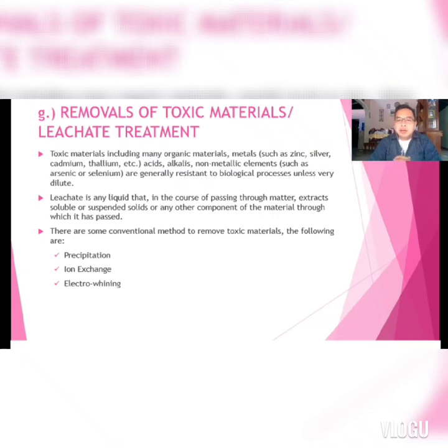Electrocoagulation is an electrochemical approach which uses an electrical current to remove metals from solution. An electrocoagulation system is also effective in removing suspended solids, dissolved metals, tannins, and dyes. The contaminants present in the wastewaters are maintained in solution by electrical charges. When these ions and other charged particles are neutralized with ions of opposite electrical charges provided by the electrocoagulation system, they become destabilized and precipitate in a stable form.